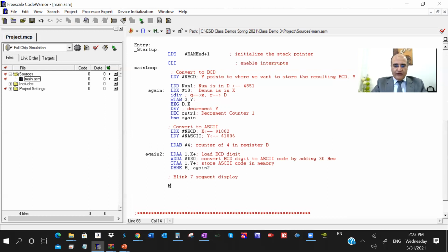output, so we move a byte immediately, FF hex, ones in all bits, to register DDRH. We already did this in the past, DDRH, and here we made port H an output to be able to turn on the LEDs. Then we want to turn on the LEDs.